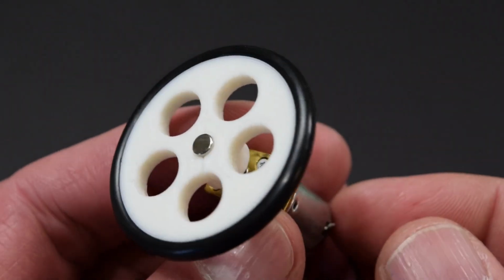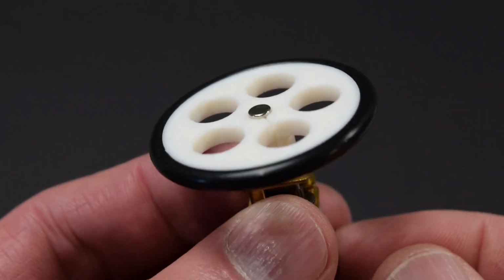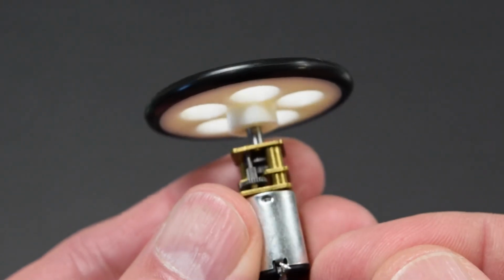And then we'll place this sensor over the top of that. Now, the poles of the magnet aren't in line with the axle or the axis of rotation. Rather, they point outwards, at a right angle to the axis of rotation. With that, the sensor can watch that movement as it rotates and easily determine the rotational position of the axle, or our wheel in this case.